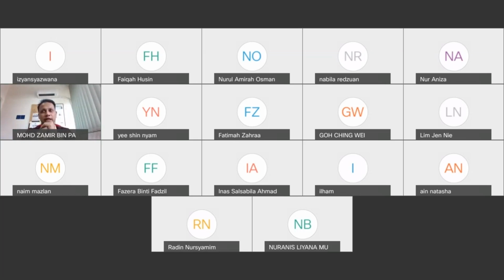So the wafers or the silicon, the ICs, will experience some sort of dopant redistribution in the profile, in the layer, in the source, in the drain, to some extent in the next subsequent high temperature processing. So that's what it means by thermal budget.